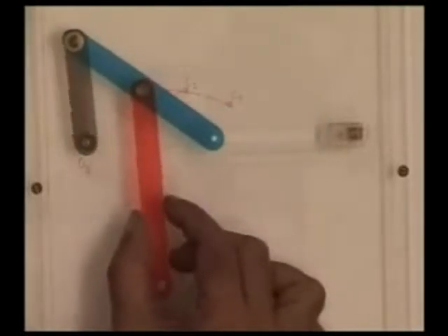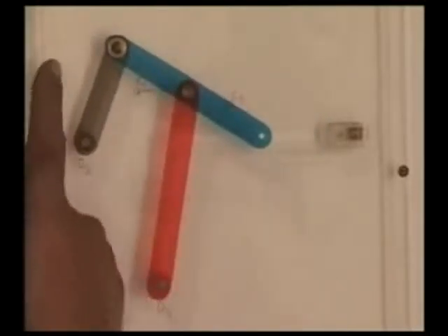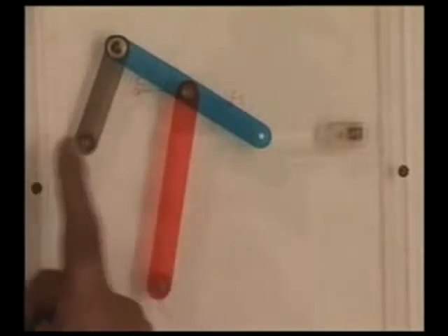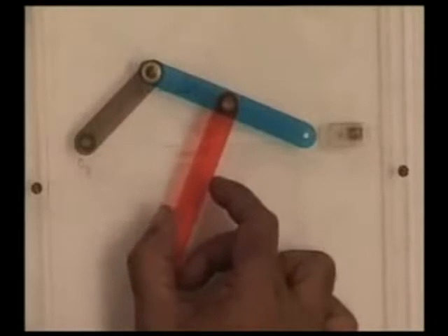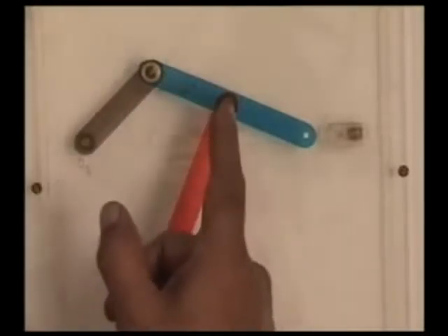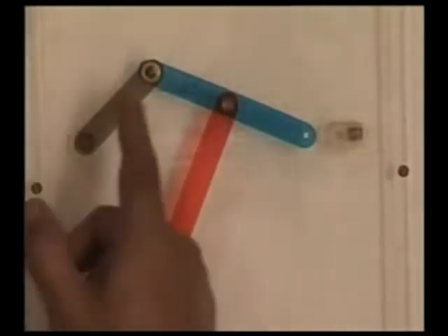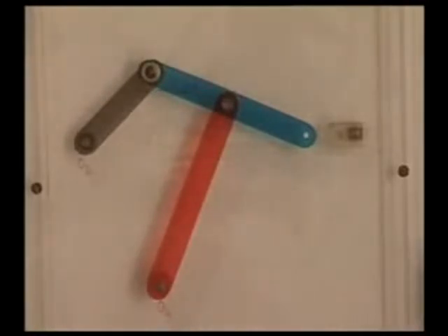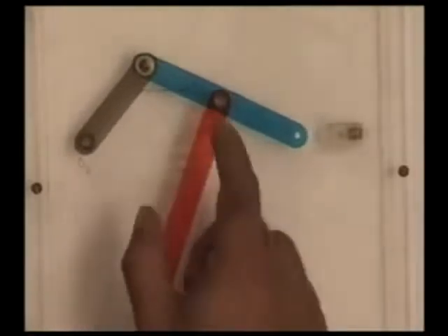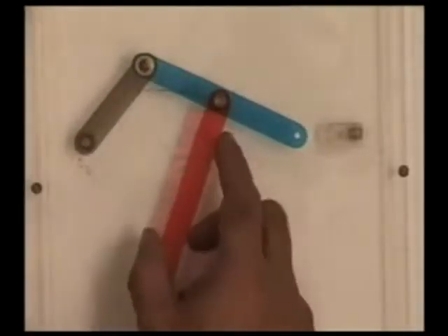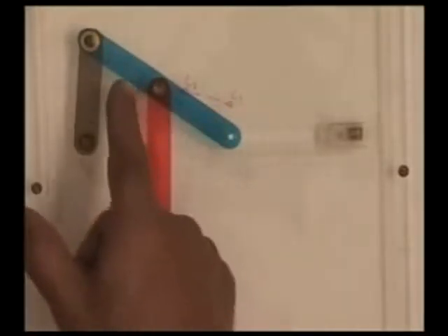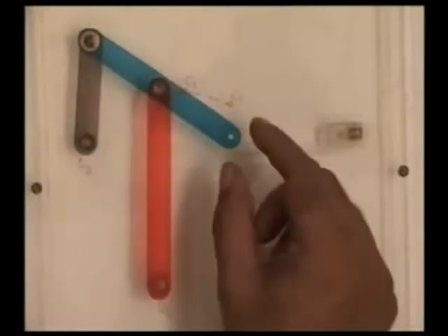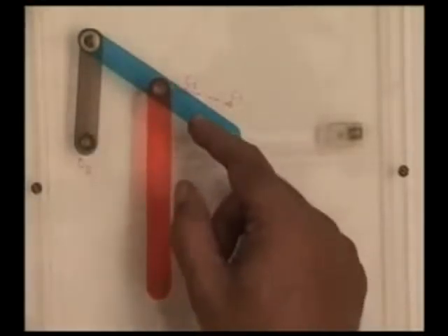And as it goes from position 1 to position 2, the movement of the crank is exactly the same as it had with the slider crank. Similarly, the movement of the crank from C2 to C3 is again theta 2, 3, which is coordinated. Now the question is, why did I take the midpoint of the connecting rod? I could have taken any point on this connecting rod and considered the 3 positions of that particular point and thought of the circle.